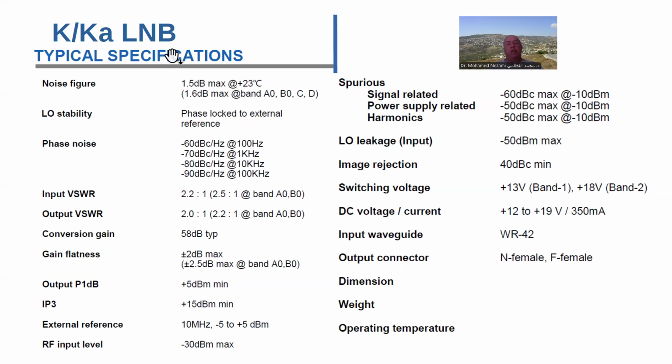This is typically what the Ka band low noise block downconverter specifications look like that we have here. So I'm going to build to this, okay? And if you check out the dominant companies for Ka band SATCOM equipment, be it Swedish Microwave, XMW, or some of the other ones, Gilat, wherever, you will see that most of them are basically coded to this.